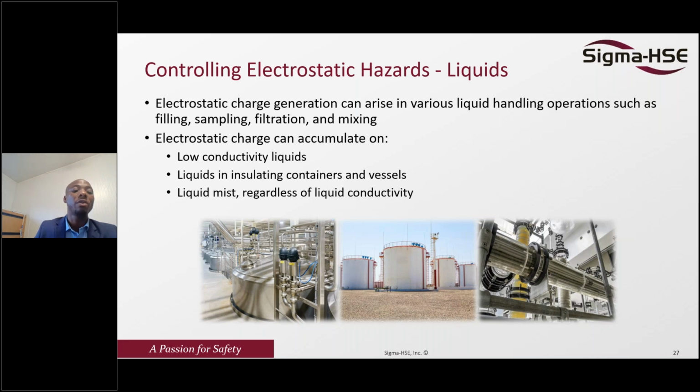Normally, if you have a low conductive liquid, or a liquid in an insulated container or vessel, even though the liquid could be conductive, if it is stored or being transferred into an insulated container, it's still the same problem. Or a liquid mist, which consists of droplets. So whether it's conductive or not conductive, it's still a hazard.